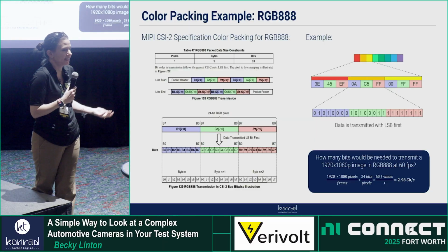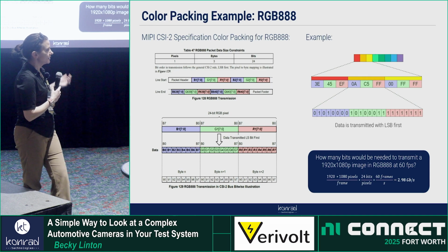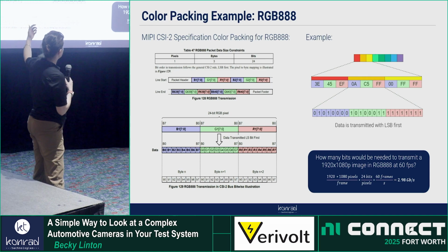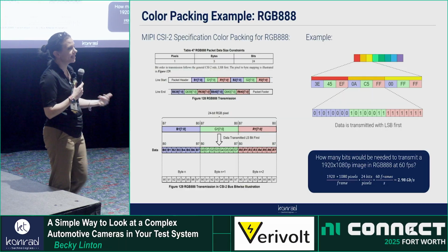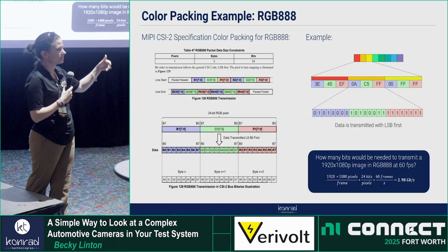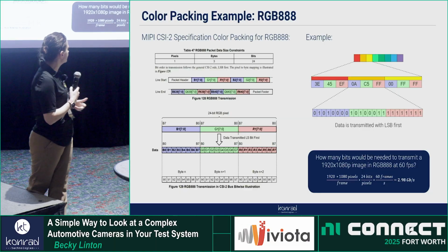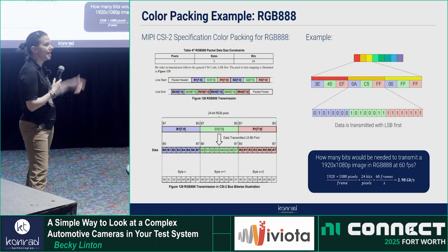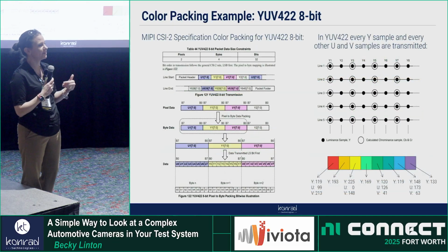We don't actually get an image. So for those of you who have never used these cards, it just looks like junk. So we have to understand how those bits were all packed together to make the pixels to build the image. And the NI getting started example kind of supports them all in a giant case structure, but we had to change things around a little bit because we actually do fault detection on the FPGA for the different types. And it doesn't fit on the FPGA. So we have different versions.